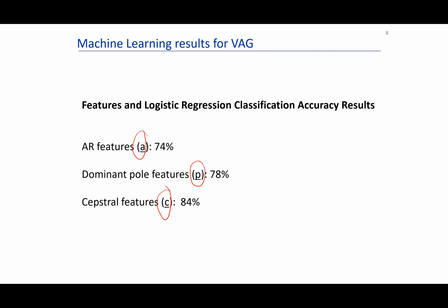This also gives an idea that in a complex process, like where we are analyzing knee sounds, which are not as characteristic and as structured as other kinds of physiological signals, the signals are non-stationary, and there is also some kind of non-linearity inbuilt in the system. We can work most of the things with the linear features like AR features and non-linear features. Cepstrum, by just doing a simple log, has allowed us to get better results.